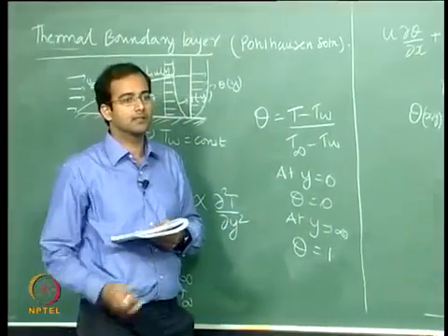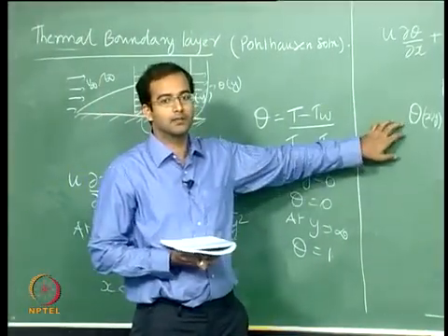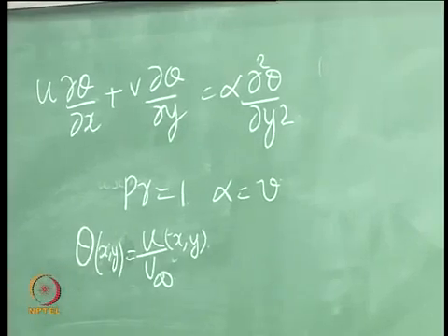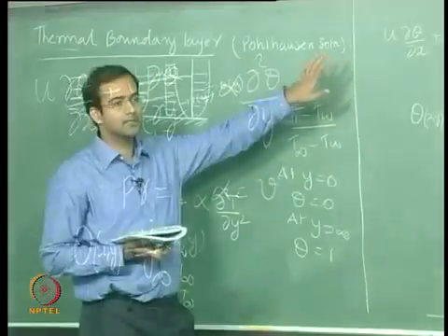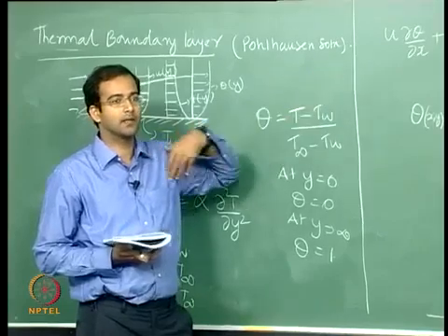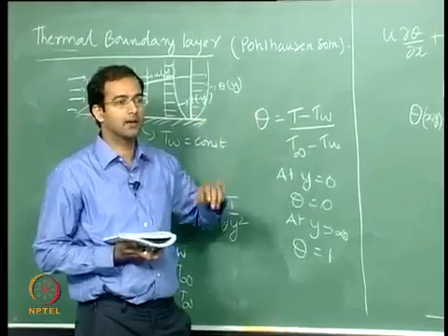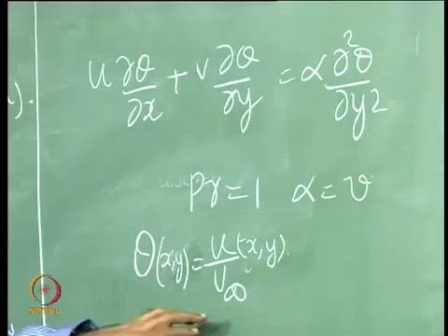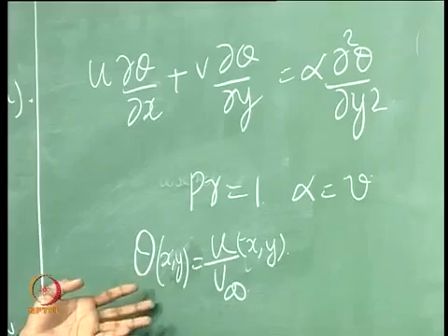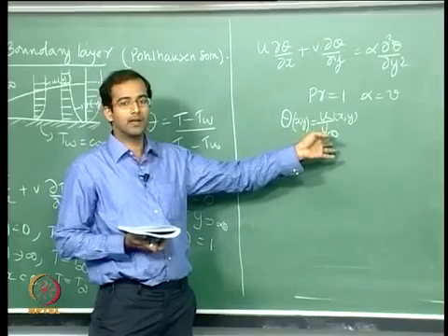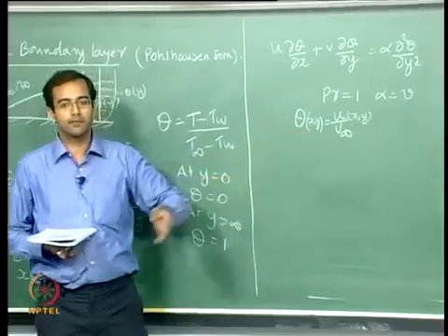Okay, so this is a very important conclusion. For a flat plate case, in the momentum equation you don't have any pressure gradient, and if you non-dimensionalize the energy equation, the non-dimensional forms of the momentum and the energy equation are exactly identical when your Prandtl number equals 1. Now when Pohlhausen looked at it, he knew directly he had the solution for Prandtl number equal to 1. The profile that you have already derived for velocity is the same at Prandtl number equal to 1.